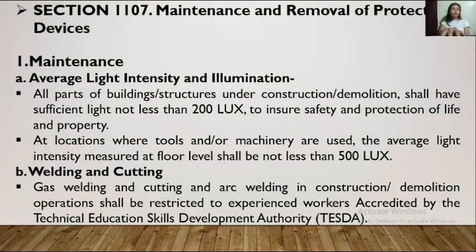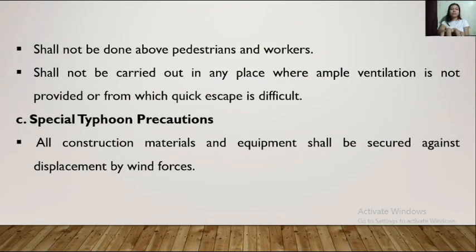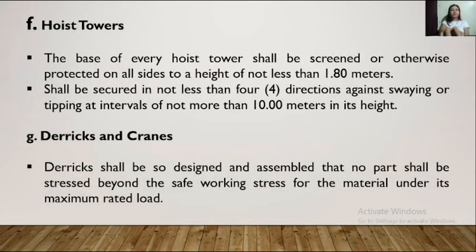Then we have also here the welding and cutting, which is arc welding and cutting in construction and demolition operations. They shall be restricted to experienced workers accredited by the TESDA, shall not be done above pedestrians and workers, and shall not be carried out in any place where ample ventilation is not provided or from which quick escape is difficult. We have also here the special typhoon precautions. Those materials and equipment shall be secured against displacement by wind forces.